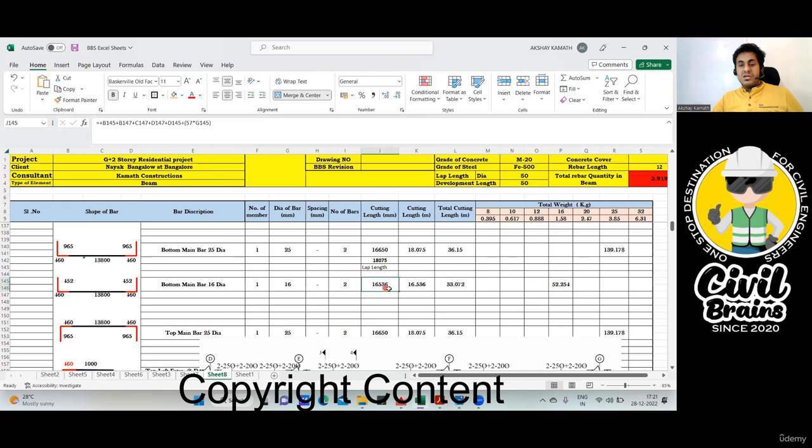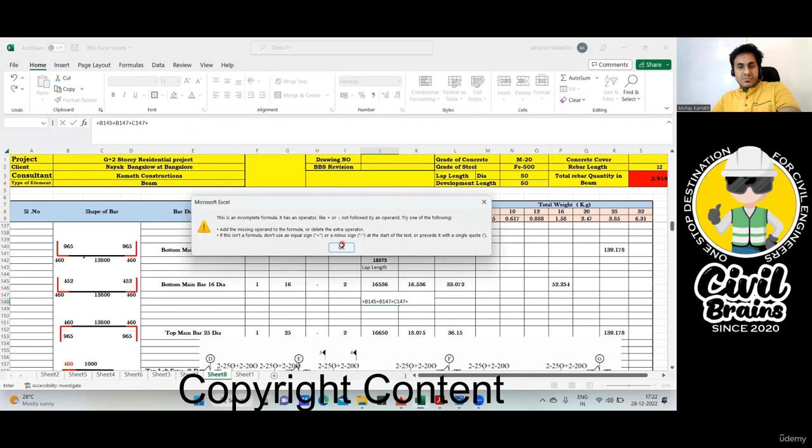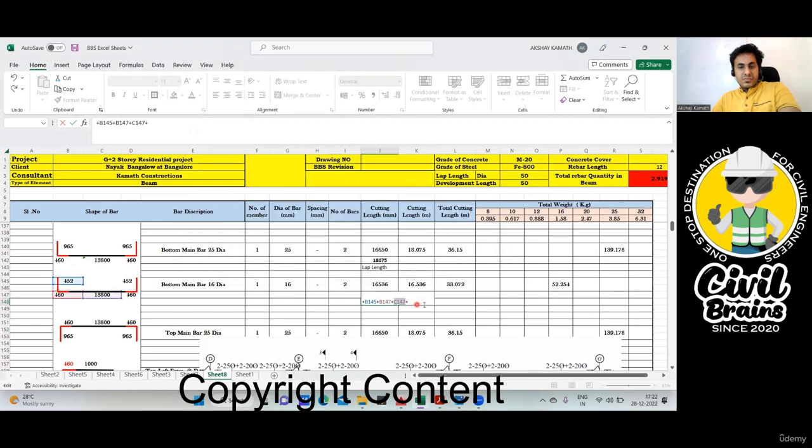And again see here, when you do this, here again I added the lap length. See here, for example, if I add this portion, 452 plus 460 plus this one plus this plus this plus this, what is the answer? 15.624, which is greater than 12 meter. So I need to add one lap. So for this answer, I'll add plus 57 into diameter of the bar. So this is the total cutting length which I should get, 16.536, which I got here. Got it? So always first do the calculation of the total length.